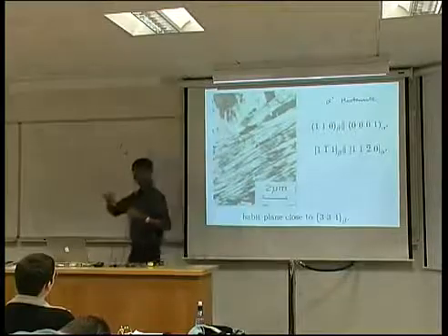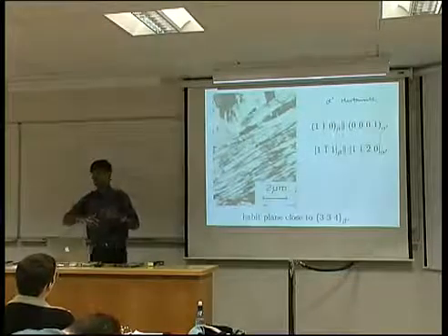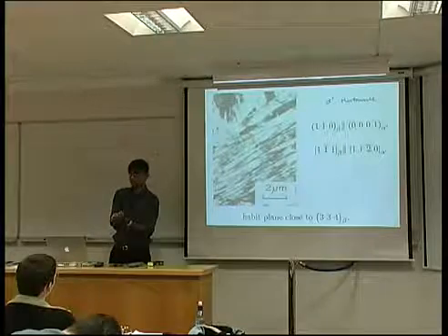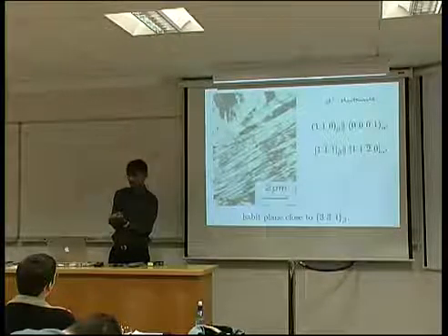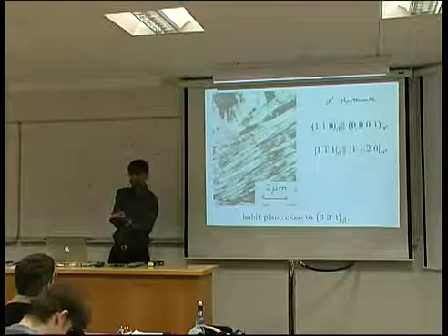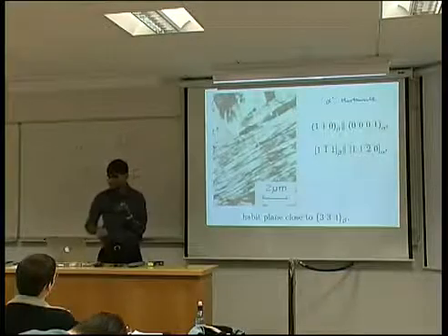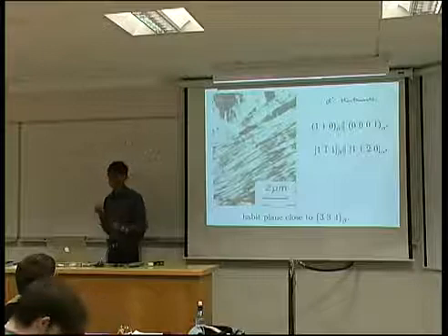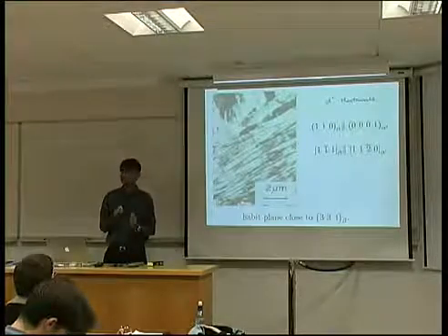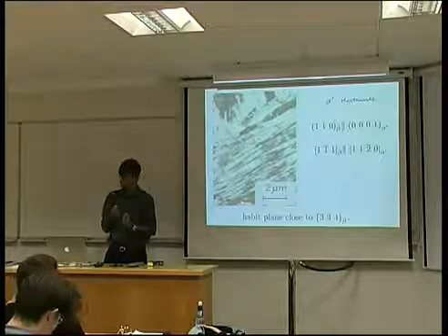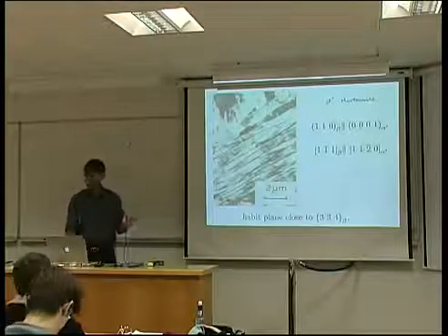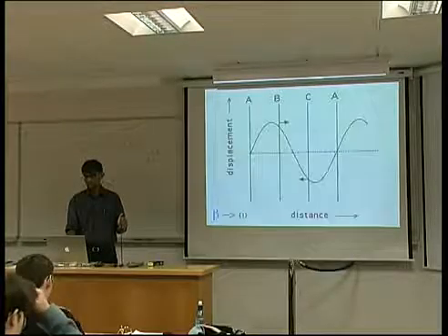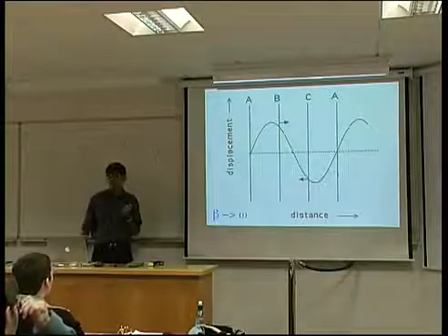And when we talk about martensite, you find that this is generally true, that the closest packed planes tend to be parallel, and the close-packed directions within those planes also tend to be parallel. So this is the martensite. But there is another very peculiar diffusionless transformation that is almost unique to titanium. It does happen in other systems, but it's of the biggest importance in titanium.